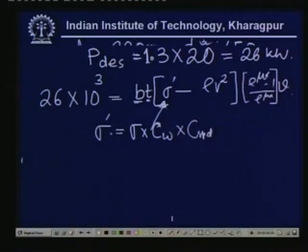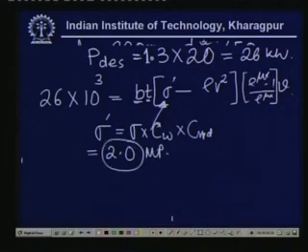Now, taking into account all this, the angle of wrap etc., the value of sigma dash can be taken as something around 2. The unit is megapascal. So this is a very standard value for the leather belt, and I am choosing this.